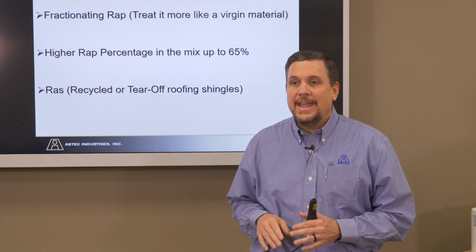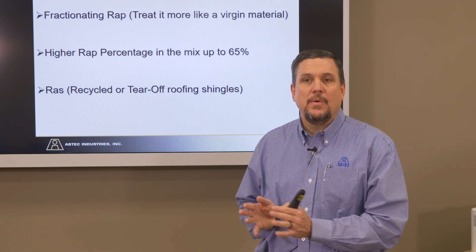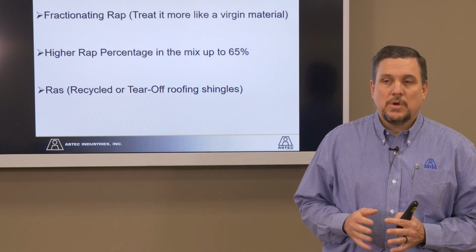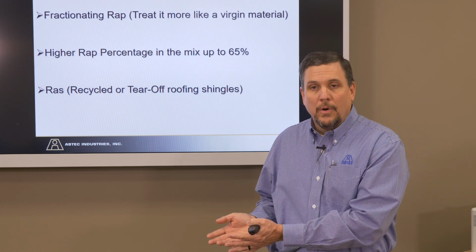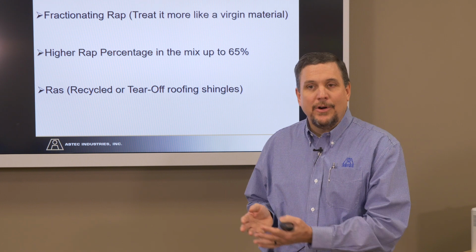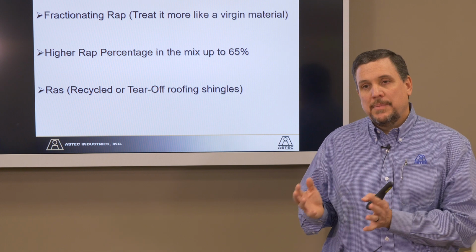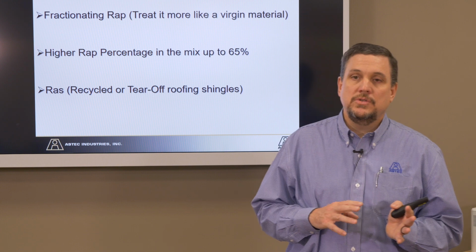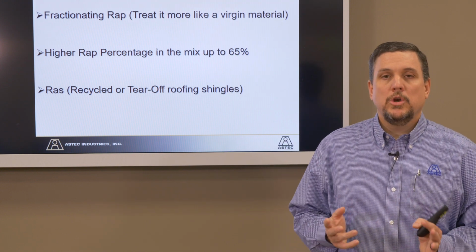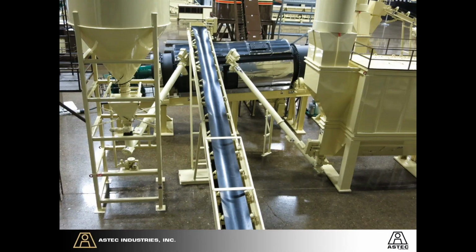When you start conveying those really low amounts, the turn down on any type of device is always the most difficult to control. So when you try to turn down a cold feed bin that's capable of putting out 140 tons an hour or more down to 4 or 5 tons an hour or 10 tons an hour, sometimes you can have some problems doing that. What you see a lot of people going to is more like a mass flow system, kind of like what you have on a mineral filler, where you're using either a weighing belt or a weighing bin that's on load cells. And you can see here's the conveyor taking it straight up into the drum and introduced into the drum.